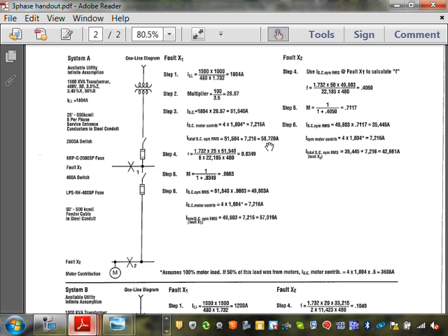Now, that's at the secondary side of a transformer. But I took 25 feet, guys. I pulled cables from here to here, 25 feet, 500 kcmil, 6 runs it looks like, and brought it to the switch here. To accommodate for the impedance of the cables, right? The cables have an impedance. You have to do this math. So you take this, here's the available short circuit. This is how many runs. This is the circular mil. This is a 480. So you got your multiplier. That gets you the impedance contribution of your cables.